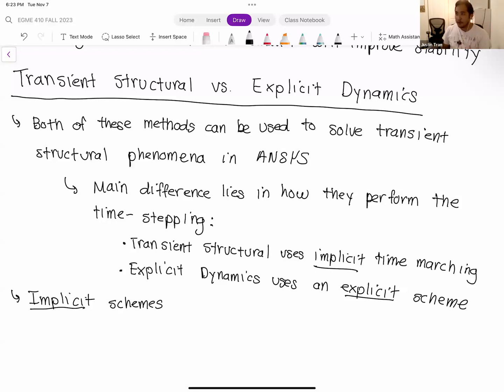For an implicit scheme, implicit schemes have the benefit of being very, very stable. Technically it still is possible to make an implicit scheme go unstable. Depending on the textbooks, they may say that it's impossible to get an implicit scheme to go unstable, which is false. It is possible to get instability with an implicit scheme, it's just a lot more difficult. The implicit schemes are much more stable, and because they're naturally a lot more stable, you're able to use a larger time step size.